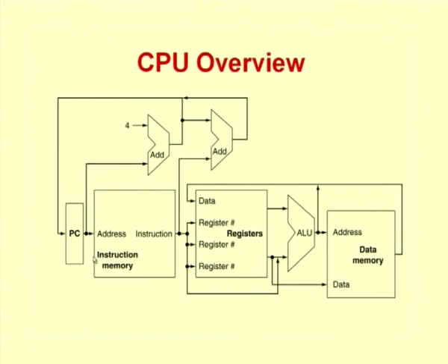Now coming to our PC part. Remember, what did we do with respect to the PC? We either add 4 to it. So I am putting a separate add unit here, which will just do the job of adding a 4, or I may have to find the effective address, which may come from the instruction, to jump to a particular location. I am assuming that location will come from the instruction. Normally the jump values we specify are relative to the program counter. That is, you add that value to the program counter to arrive at the effective address. So the PC value that you have already added 4 to, ready to execute the next instruction, we either take that value, or we add this relative address that is specified, add the 2 values, and then that value has to be stored into the PC. This is what we would roughly need to do.